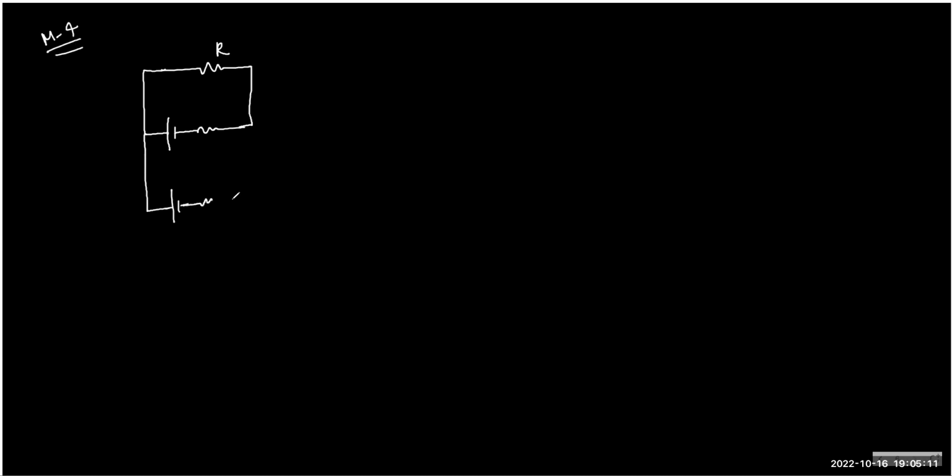So we have seen Millman method, the theorem where directly you can apply the formula. And I'm keeping the same example so that you can correlate things. Now, there's a trick. If you want to apply KCL, you need to know the potential of every terminal. Okay. So what I can do is I can choose this as 0 for some weird reason, and this I will call V. Why I'm doing this? Because once I do this, I'm at ease of assigning the potential of every point of the resistor.